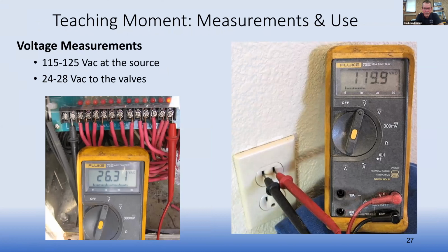Again, one of the things that we could do would be to test voltage this way. And the things that we're going to be dealing with the most when we're doing troubleshooting would be power in, power out. Do we have power to the controller? That would be a matter of checking the actual plug that it's plugged into, and are we getting 115 to 120 volts AC at the source?